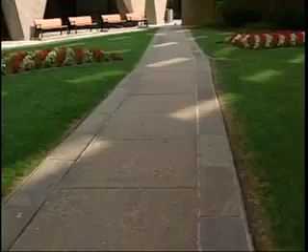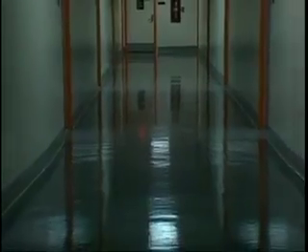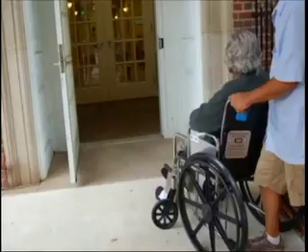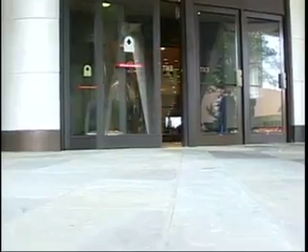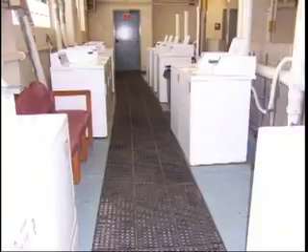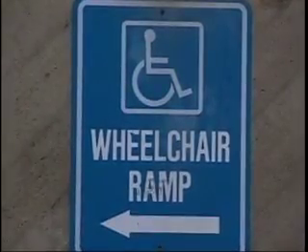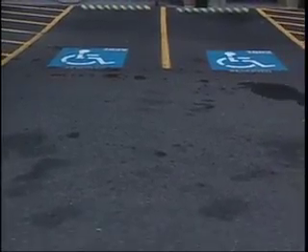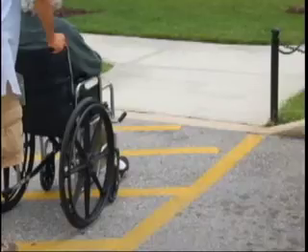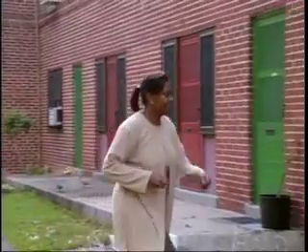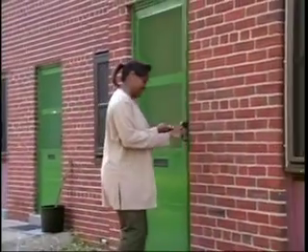An accessible route includes all walks, halls, corridors, aisles, and any other space that connects an accessible unit with accessible buildings, facilities, elements, and spaces on the same site. An accessible route shall also be provided from public transportation stops, accessible parking, and sidewalks to the accessible building entrance they serve. However, an accessible route cannot include stairs.